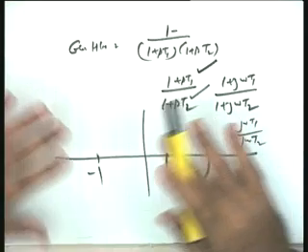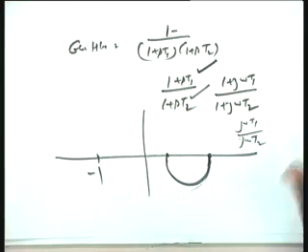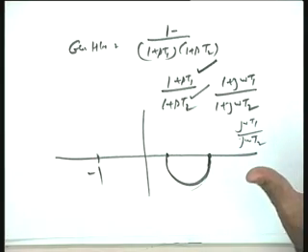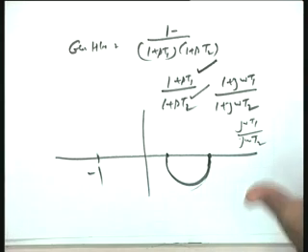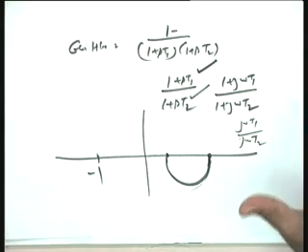And we say that the parameters of the model can be changed because this much gain margin or this much phase margin is available. So if you study the stability of the system, it will turn out to be stable for all values of T1 and T2, and therefore the terms gain margin and phase margin for such a system appear to lose meaning.